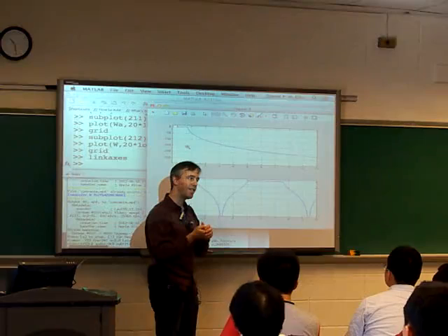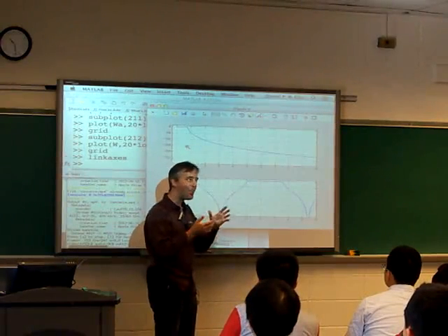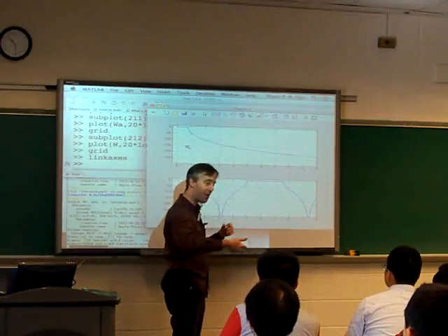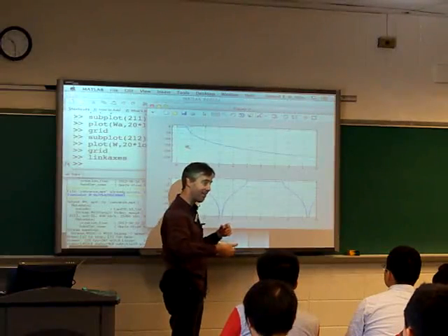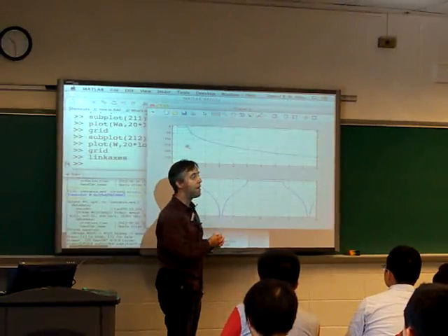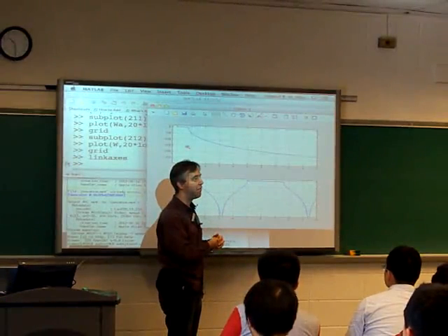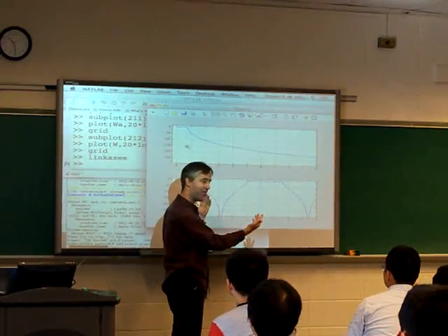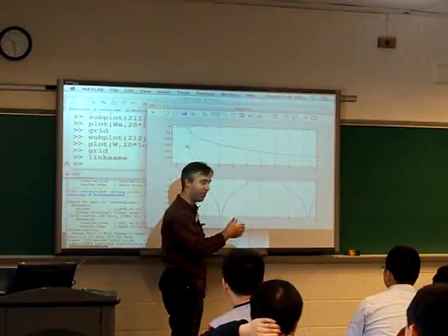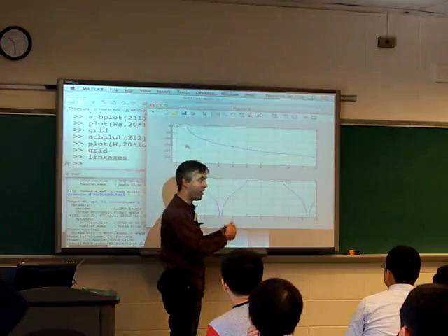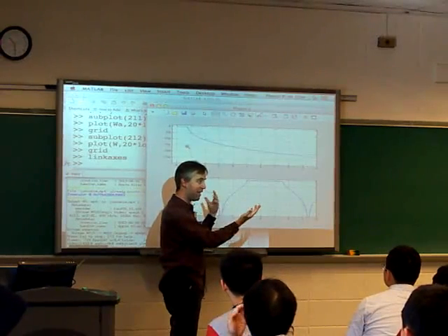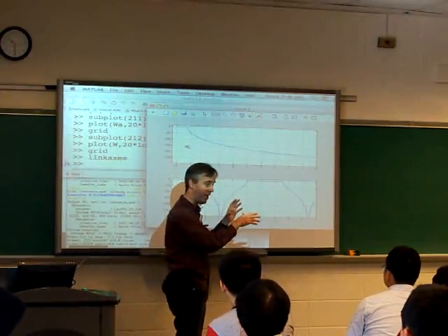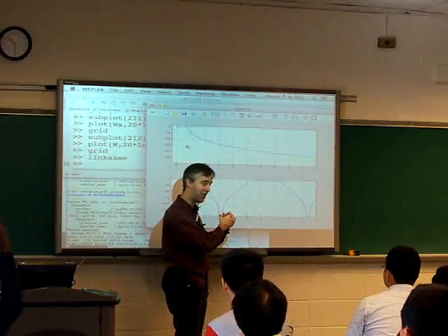Because the positive frequencies correspond to these complex sinusoids, right, spirals. If we want just a real-valued thing, we've got to add in the conjugate versions of those, which are the negative frequencies. That gives us a real sinusoid, and then by changing the relative phase of the real and imaginary parts, we basically vary the phase of the sinusoid that we get when the imaginary parts cancel out.